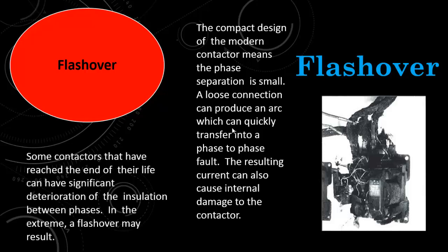Another reason is that some contactors that have already reached their end of life can have significant deterioration of the insulation between phases, and in the extreme case a flashover may result. So this is all about the main reasons for failure of the contactor. In the next video I'll come up with the main solution, how to avoid these failures by applying proper maintenance procedures for the contactor.